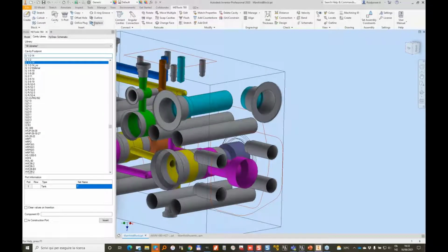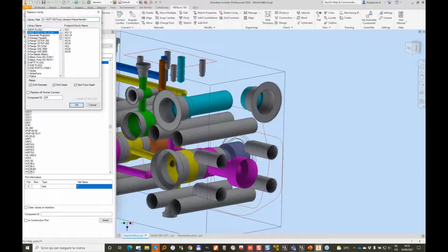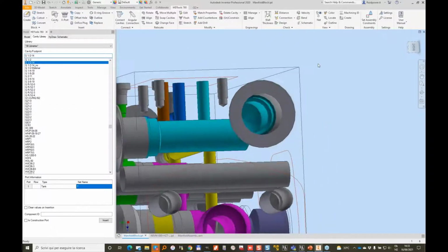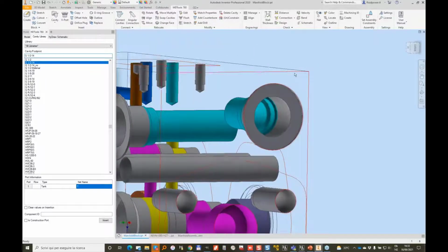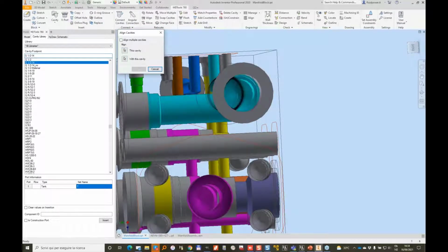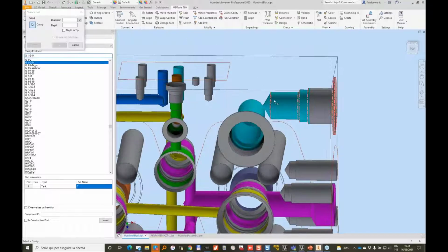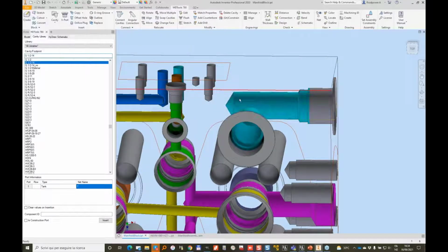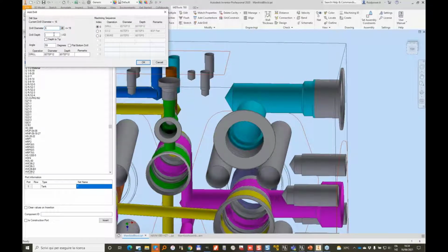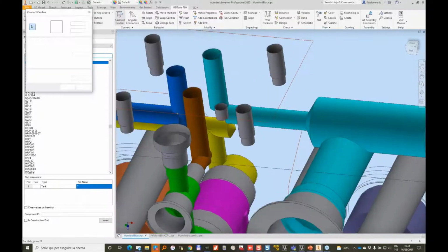That's a different cavity. Let me replace. I took a wrong cavity. That's a particular one. Let me replace this cavity with a standard G1/2. And this is okay. Let's say that we can align these 2 cavities. There is enough room. We can stretch this drill up, and we add a small drill. Add drill to this cavity. Let's say we add a 6mm diameter by 80. Let's make it 90, and that's fine. And we connect it.